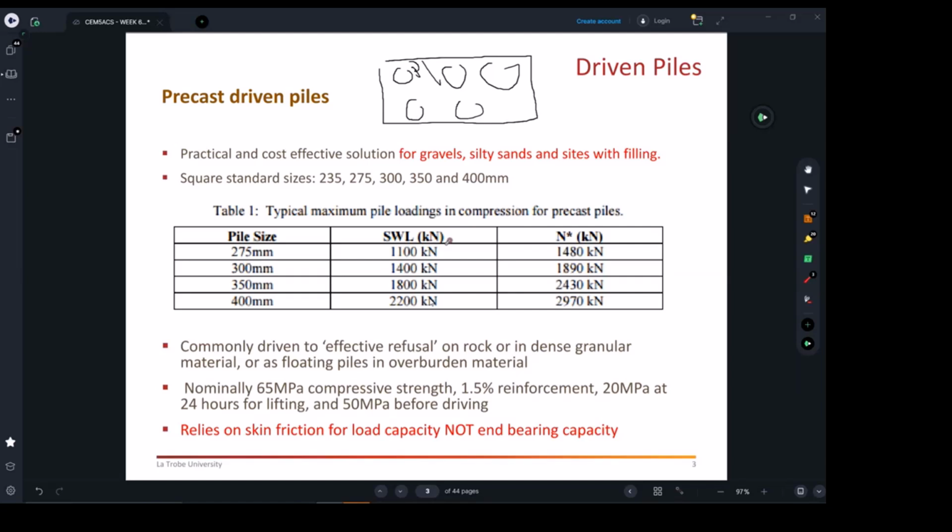During the construction process, they're going to verify the load the engineers wanted the building to be supported on. So yes, the engineer is going to calculate all the loads to the footing, but on their drawings, they're going to say the piles should take this many kilonewtons as a service working load. Now that's what construction engineers typically work with. This is the ultimate, in case they also want to specify the ultimate.